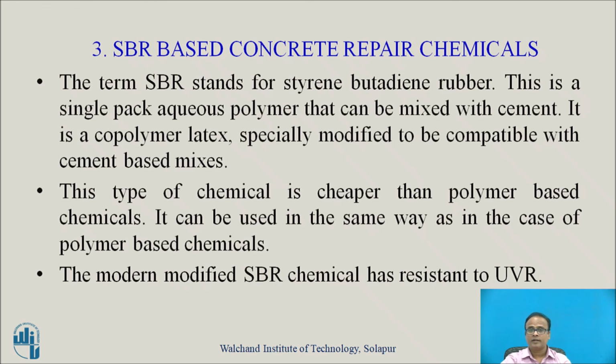The modern modified SBR chemicals have resistance to ultraviolet rays. So when the surface of concrete is open to atmosphere or subjected to some ultraviolet rays, then we can go for modified SBR chemicals.